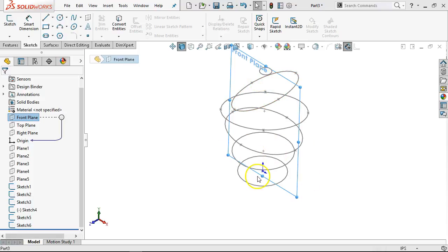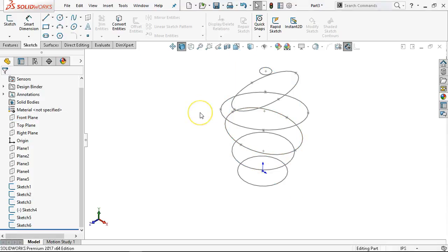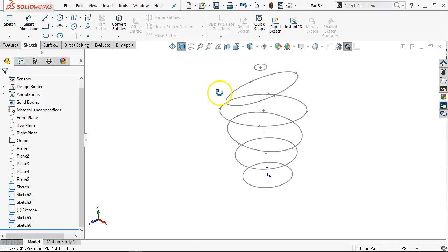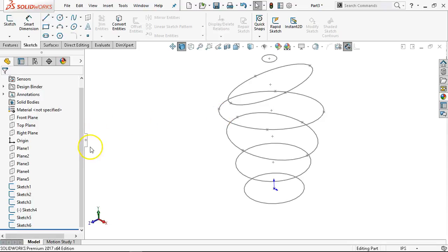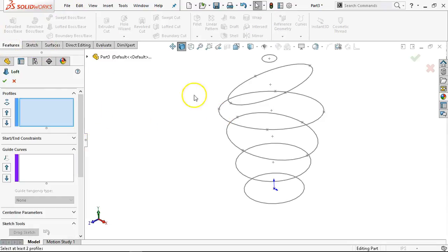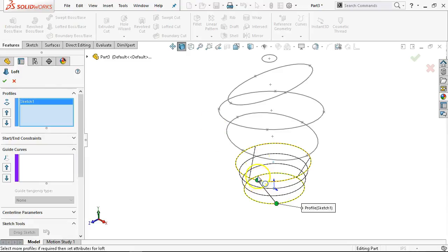Each of the circles has an infinite number, or no nodes to consider. So if we really want to manage this, I should put 4 points on each of those circles, to be able to match up to the 4 points on the ellipse. So let's just see what it generates, and we'll go through that process. We're not going to have guide curves. We're just going to go to the handles.